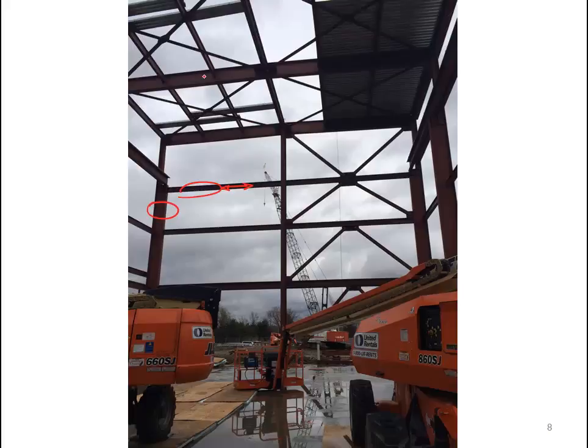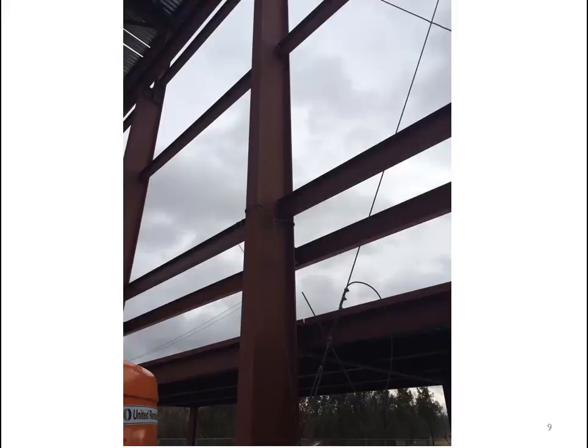In fact, when you look at the roof beams, you see that the roof beams are going to be much closer in terms of depth to the depth of the columns. And that makes more sense because those beams are going to actually be carrying flexural stresses. Here's another photograph showing the beams, in this case resisting mostly axial loads and framing into the columns.